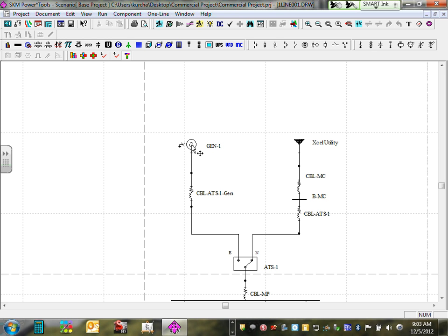So I was naive at that time, giving my calculation to my boss. He just looked at it, he said, no way you can get this short circuit. Go review your calculation, just from the numbers. Reviewing the calculation, it ended up being 100 feet versus 100 mile. Very easy. I should have changed it into feet before I put my numbers. Garbage in, garbage out in all software. Make sense? So when you guys are looking, make sure, does it say kVA or volt amp? Does it say amp or kilo amp? Always look, it makes a major difference in the calculation.